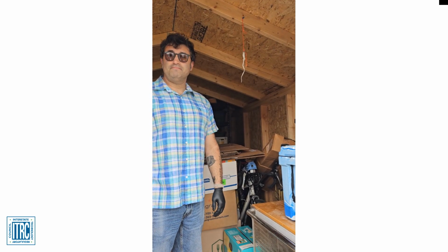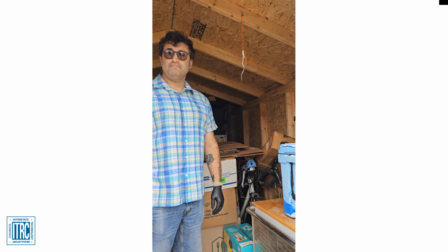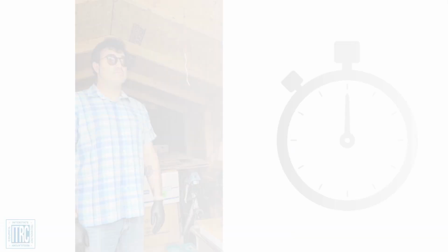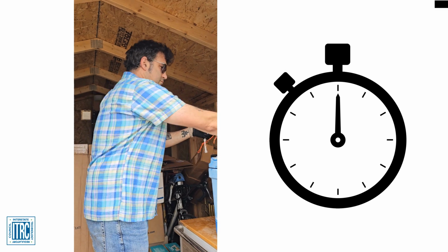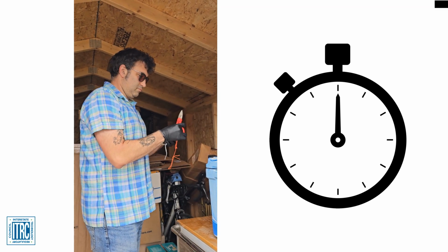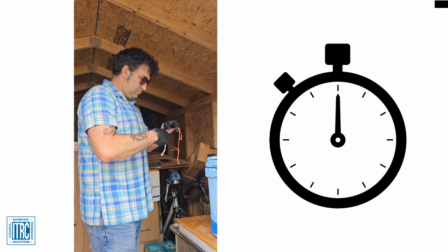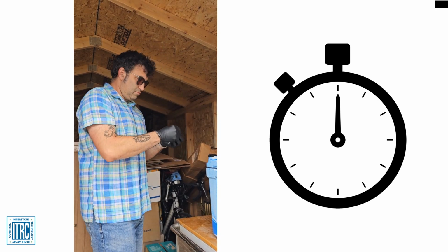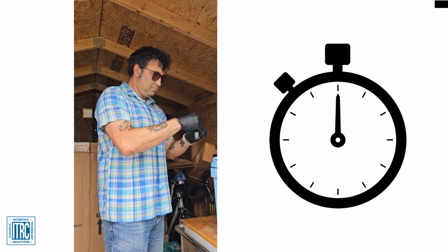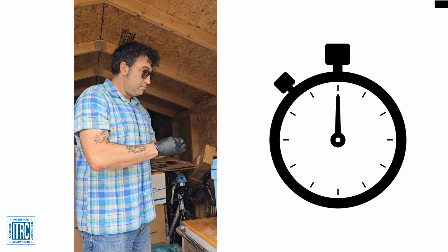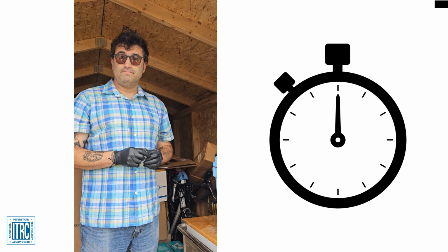Once deployed, the field personnel should record the sampler's serial number, the installation date, and time on a sampling log. The samplers are then left to passively collect air for the deployment time, which can range from days to months. Once the sample collection period is reached, the field personnel will remobilize to the site to retrieve the samplers. Remove the securing device from the module. Wipe the sampler clean if necessary, using a clean cloth rag or paper towel, return it to the corresponding glass vial and log it onto the provided chain of custody. The samples are packaged and then can be shipped to AGI's laboratory for analysis.